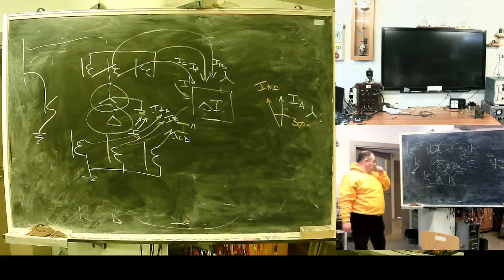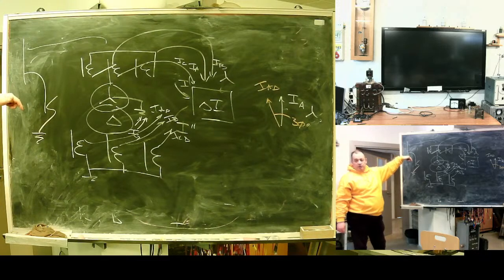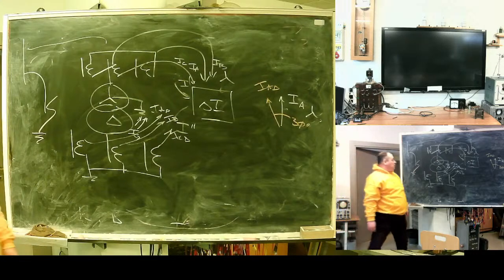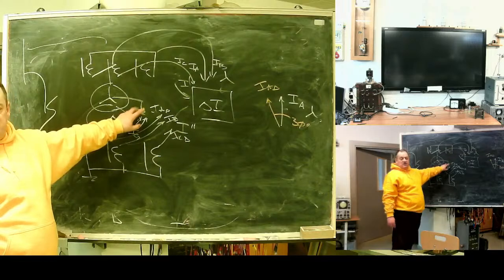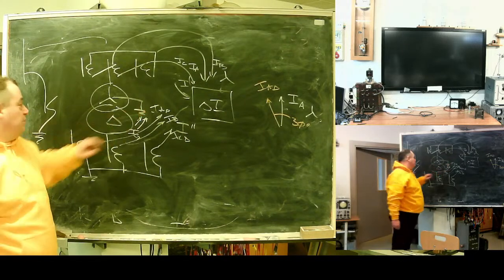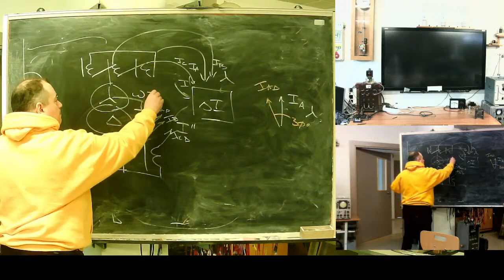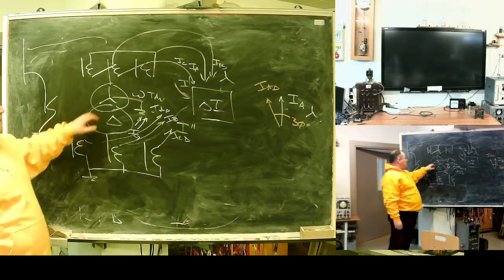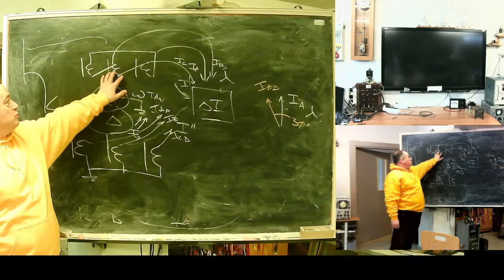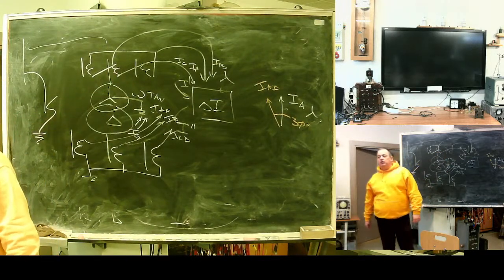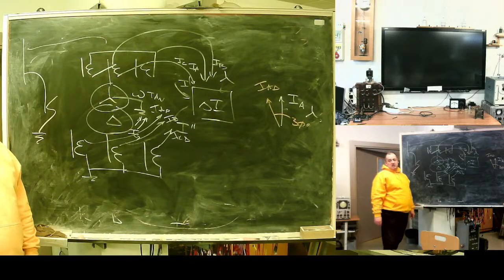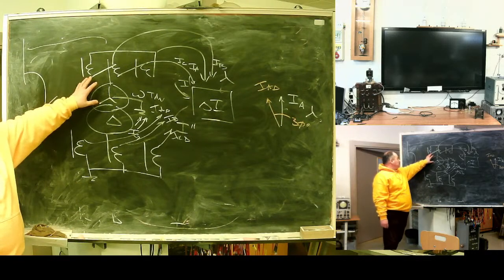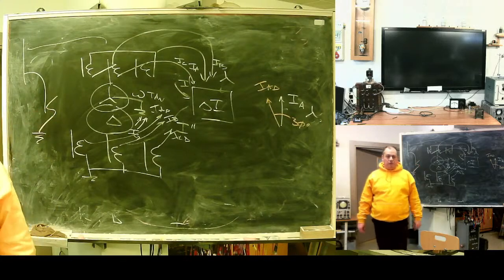Problem, transformer protection will see current inflowing but nothing outflowing. There will be imbalance and it may trip falsely. To prevent it, you need to either check for zero sequence, or on this wire you may place a current transformer here. You may check for zero sequence, but one of the tricks, it's old school. Use this delta connection, it will not pass zero sequence current through it. So, transformer protection will be immune to outer ground fault.